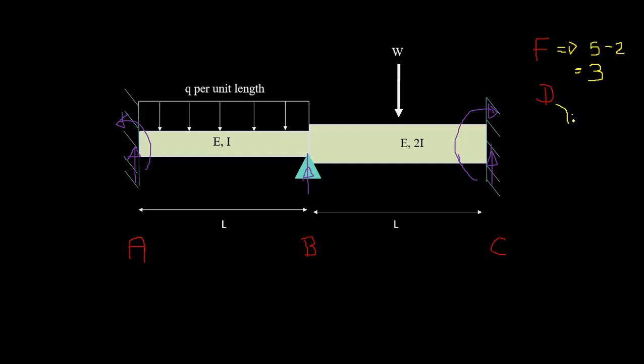But what happens in displacement? Here, the kinematic indeterminacy, the unknown displacements are 0, right? Because it's a fixed support. You know the vertical translation is 0, horizontal translation is 0, and the rotation is 0. And 3 displacements, and all of them are 0. That means those are no longer the unknowns. Those are known values. All things are 0.